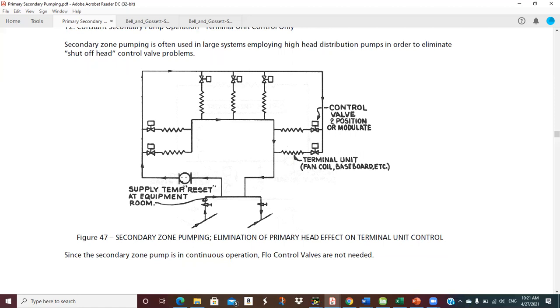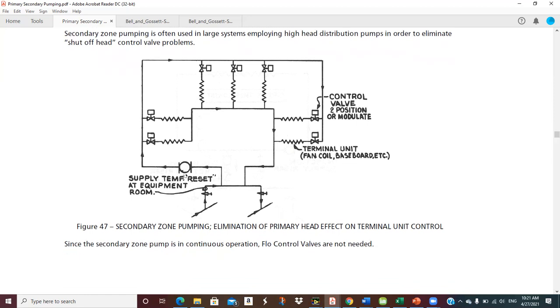Now, of course, you've got two, four, so you've got seven. I mean, what are the chances all of them are going to close? I don't know, but it could happen. And, you know, Murphy is always lurking out there. Whatever can go wrong will go wrong. And it'll probably be on your first design job and it'll bite you in the tail. And somebody will yell at you because, oh yeah, you deadheaded the pump and it burned up. Oh, dadgummit, I knew I forgot that. You know, whatever. So you would have to consider that in this case.